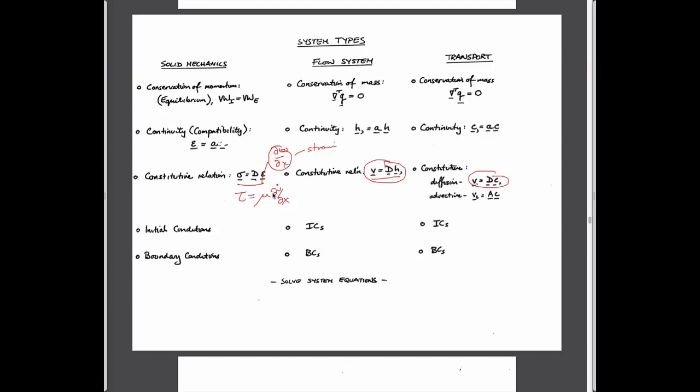Because now, in all of these systems, the reason that we can solve them quite easily using finite element methods is that they all look very similar to each other. Conservation of mass: mass in equals mass out, and if they don't balance, it's equal to accumulation. A constitutive relationship, which is Darcy's law, takes care of frictional losses, and then we apply boundary conditions to it. In solid mechanics, the conservation equation is a force balance. It's actually the equilibrium equations, which in our work we'll do by looking at the concept of virtual internal and external work. It's just an easier way to develop the equations.